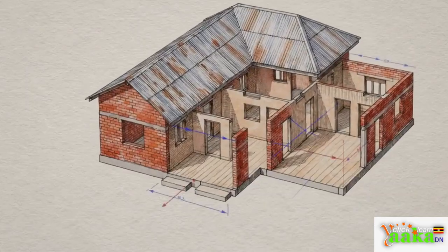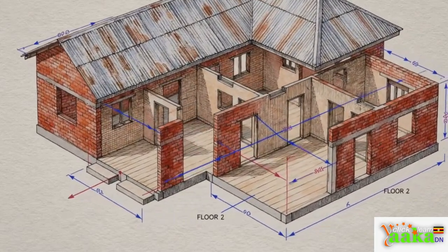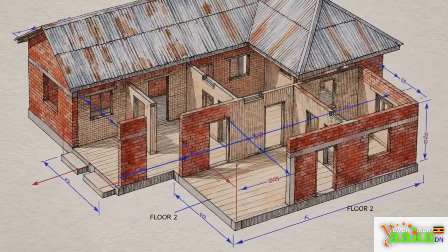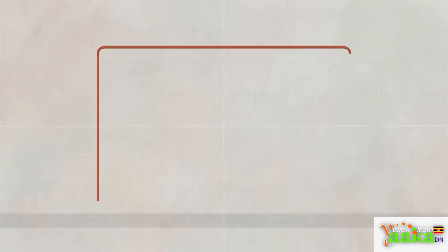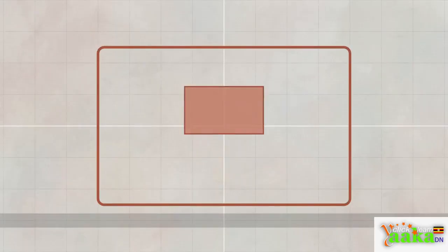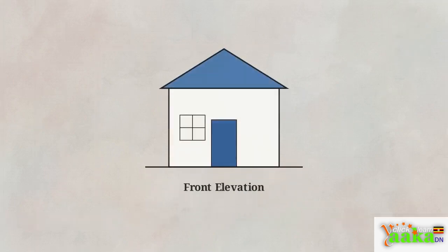The first step in deconstructing a building is separating that single 3D structure into distinct isolated flat viewpoints. We start with the most zoomed-out perspective. This top-down view is the site plan. It maps the macroscopic layout, showing property lines and access roads. For your exams, you must always include a clearly labeled north point, which orientates the entire property to magnetic north.